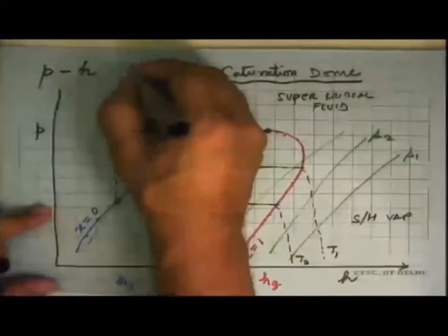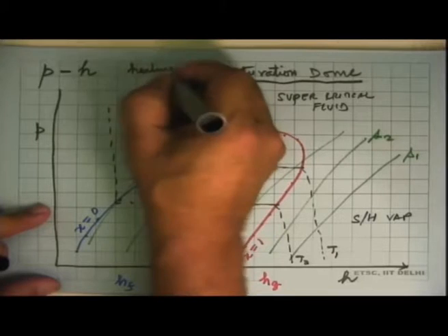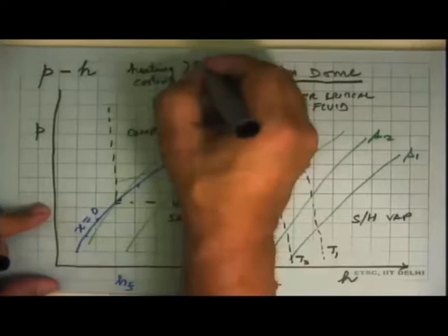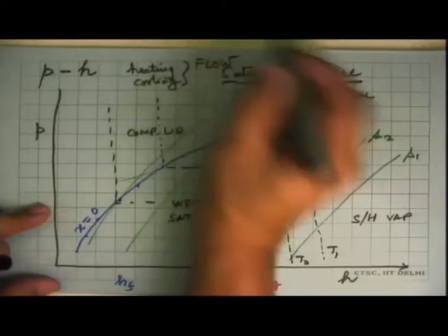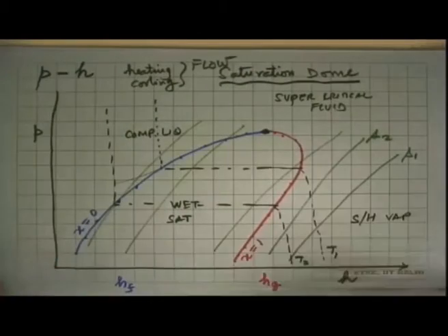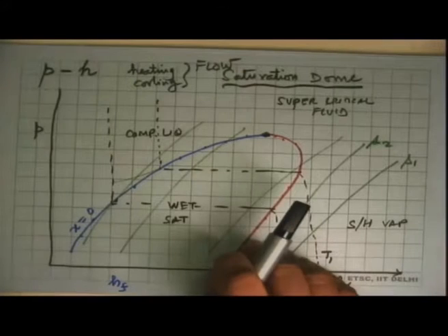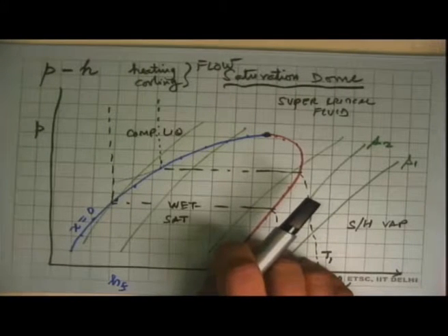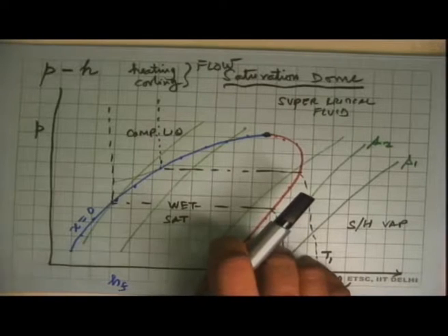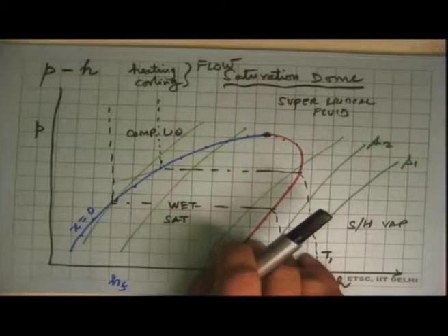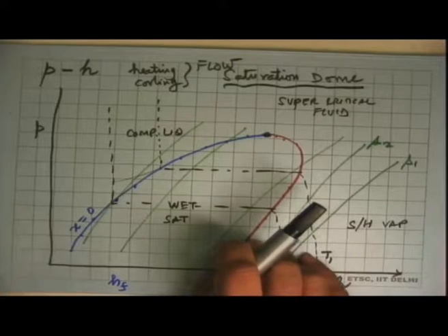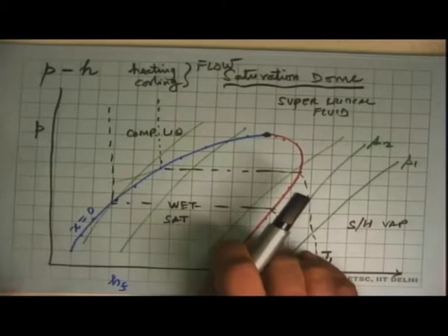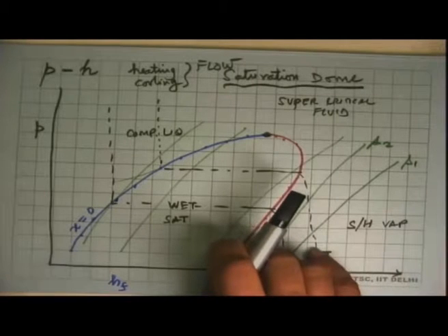That processes like heating and cooling, especially in a flow process. An example of that is, say, the air conditioner evaporator, in which we are pumping in the substance, it goes through all the tubes, and comes out. In the real case, there will be some pressure drop, so the outlet pressure will be slightly less than the inlet pressure. For the time being, let's not worry about it and say that there is no pressure drop.